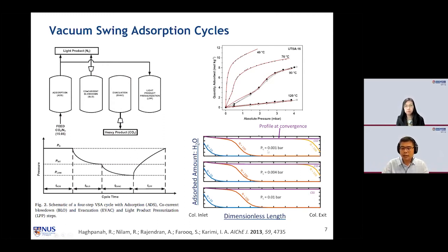And in this case, if we apply this amount of pressure as a vacuum, after 10 cycles of adsorption and desorption, this would be the concentration of the residual water inside the column. You can see that water starts to accumulate inside the column after 10 rounds of cycles. After 100 cycles, the water front will propagate along the column. After 500 cycles, the column is almost saturated with water. Under the cyclic state equilibrium, CSE is cyclic state equilibrium. Under this equilibrium, the whole column will be fully saturated with water.